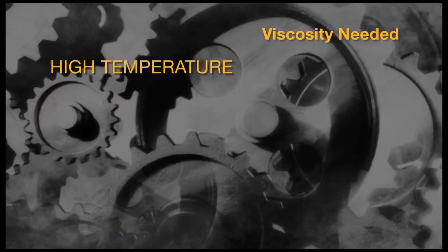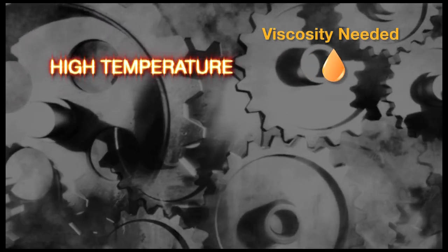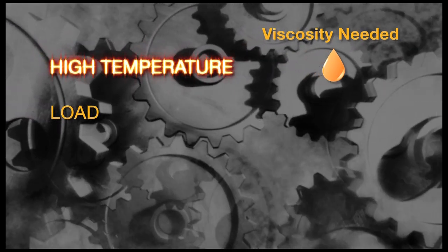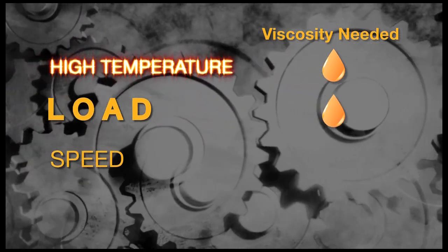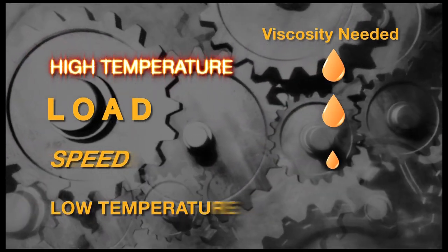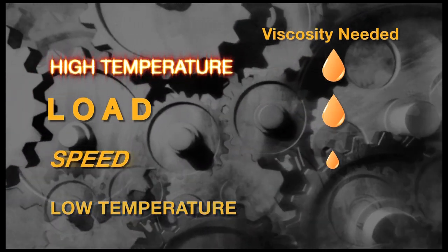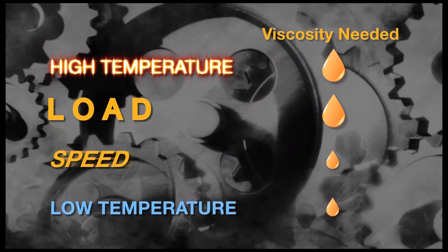For high-temperature applications, you would need a higher viscosity lubricant. For higher load applications, you would also need a higher viscosity oil. For higher speeds, you would need thinner oil, a lower viscosity lubricant. And for lower temperature applications, you'll also need a lower viscosity oil.